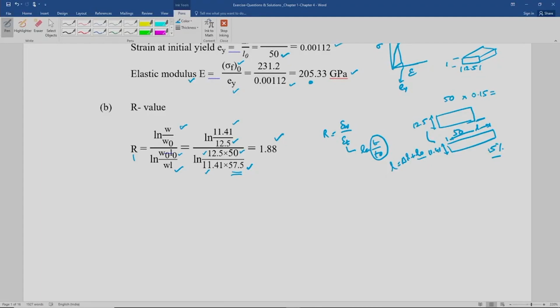And then the surface roughness generally plays a little role in evaluating the final component's performance. And then strength actually decides the stiffness of the component, that's the only thing. Then elastic modulus is going to control the spring back of the sheet. In one way it is going to affect the spring back of the sheet, which should be minimized, and accordingly you have to choose the material's Young's modulus. So just to summarize, this is what we have done, and then we will move on to the next chapter in the next class.